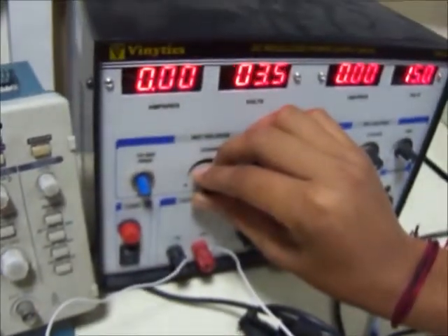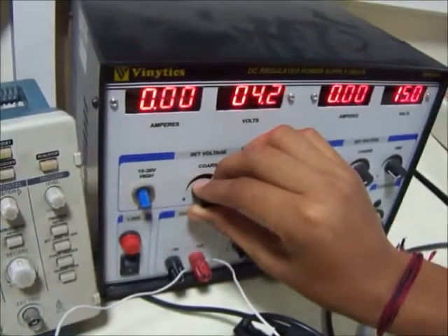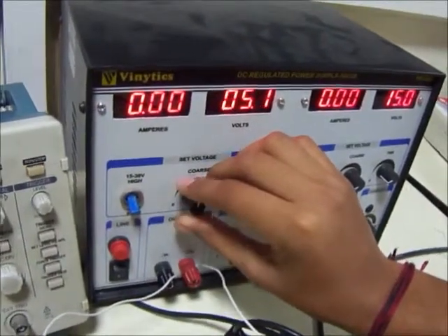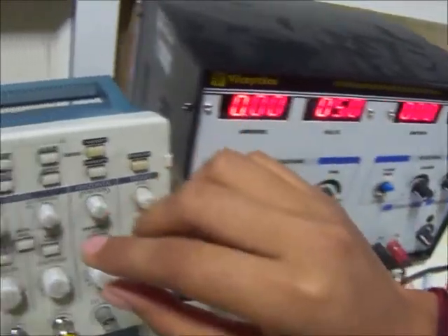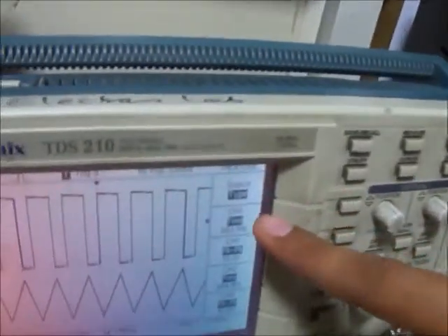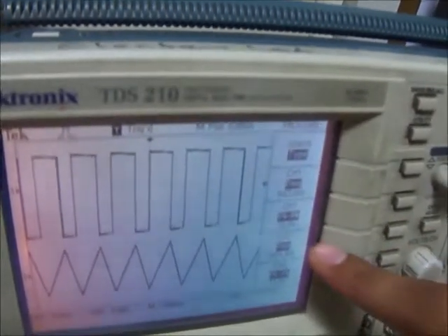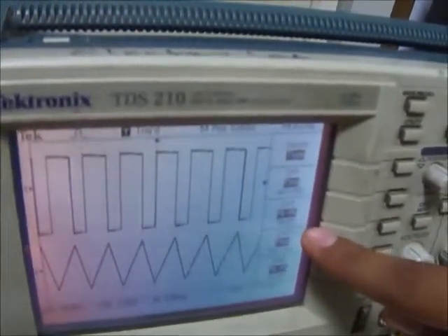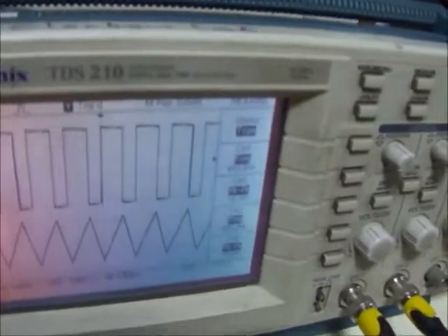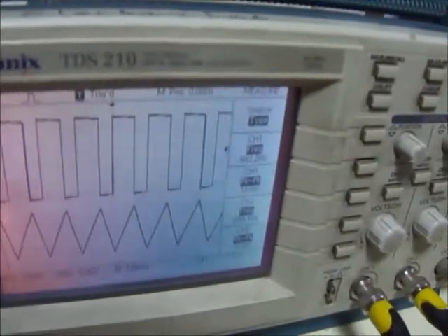We increase our control voltage to 5 volts. The resulting waveforms have a frequency of approximately 684 Hz. Thus the frequency is increasing as was reasoned earlier, and the peak to peak voltages remain the same with the control voltage.